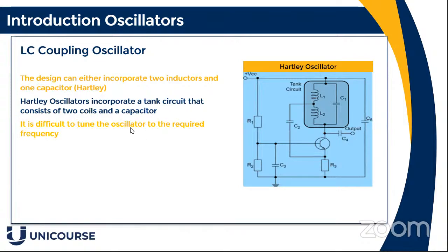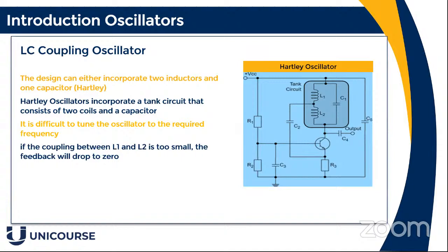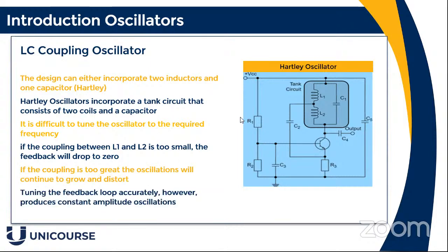The problem with this sort of circuit is it's difficult to tune. And when you're using it for a radio frequency, an RF transmitter, you want something which is quite stable. But it does work. The L1 and L2, very cool, and it's a bit fiddly to set up. I've tried one of these years ago. Not too easy to set up the right frequency. So this is the basic circuit.